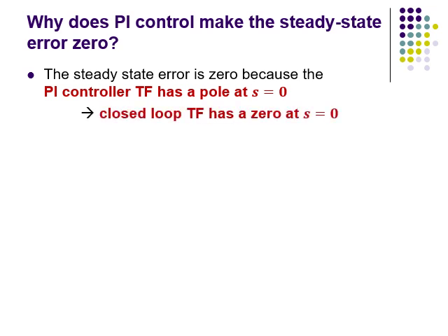And what it means is that if you calculate the closed loop transfer function of the system, we find that the s in the denominator of the controller transfer function ends up in the numerator of the closed loop transfer function. And so the closed loop transfer function has a 0 at the origin of the complex plane.